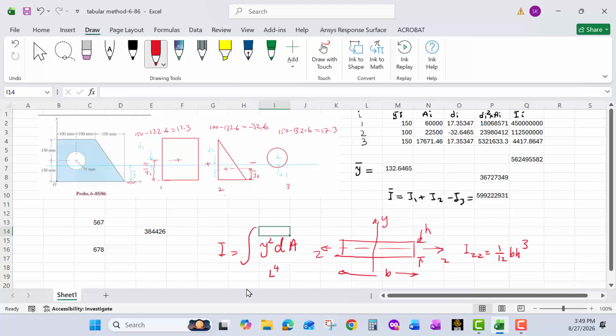Y bar is serving as a reference. So this is exactly the neutral plane where the fibers of the bending segment are neither under tension nor compression, and on both sides of this axis or plane the fibers are deforming in tension or compression.